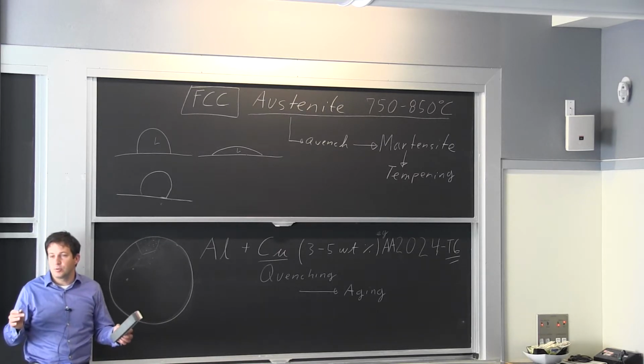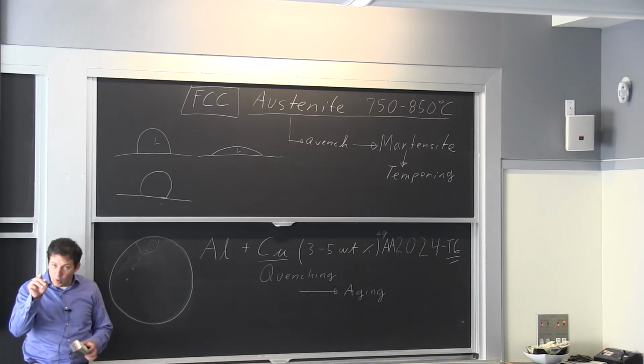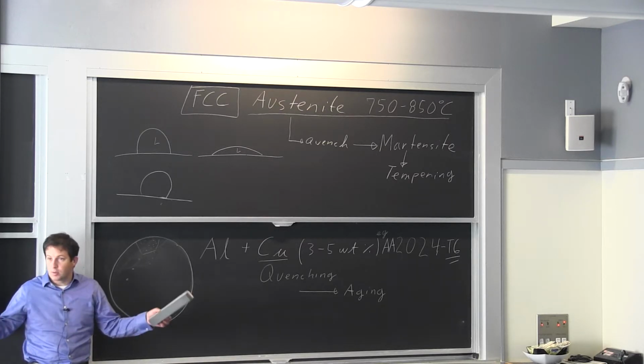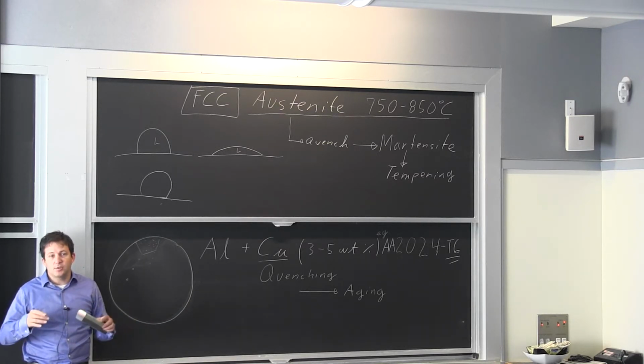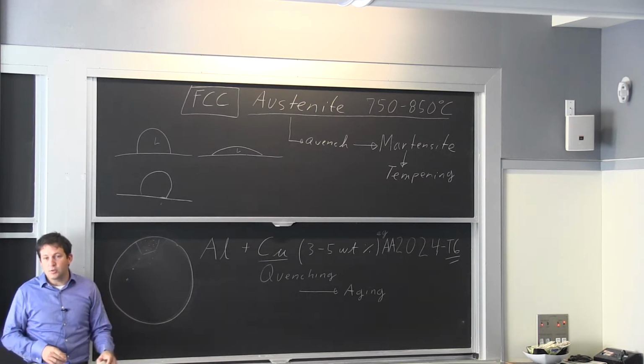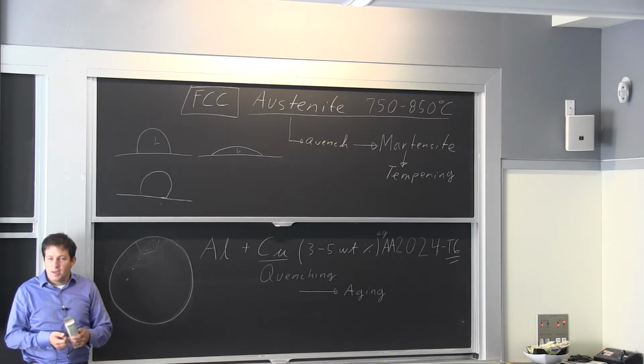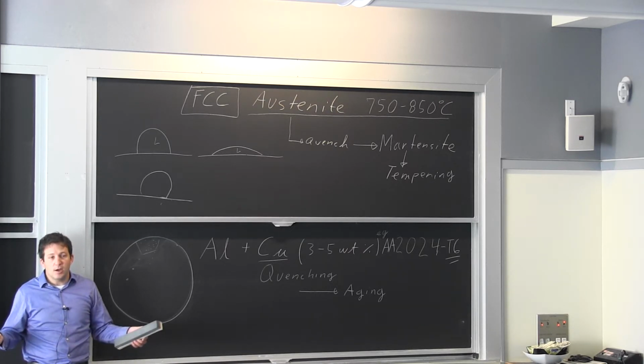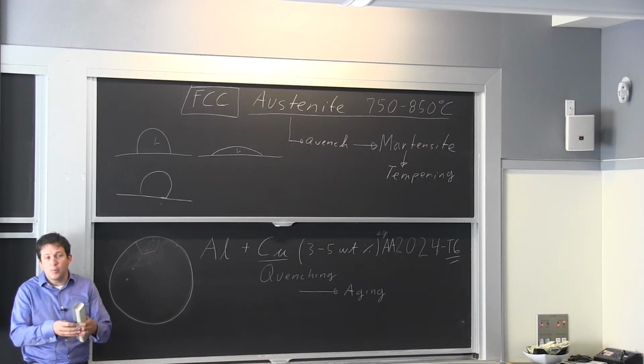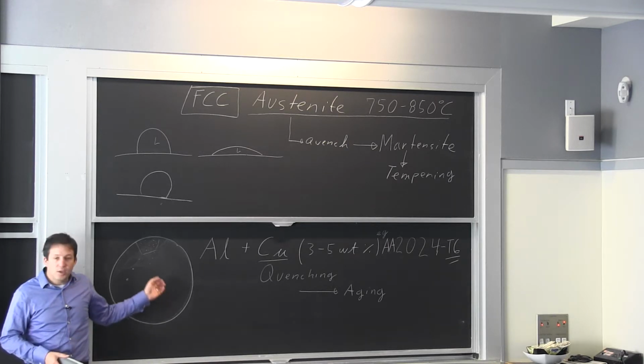If you're at high temperature, you have so much diffusion that if you have one little particle that starts forming, it's going to grow on you. And therefore, we can't just do it by cooling. That's why we quench. And when we heat back up, the condition we have is there's a big driving force. There's a lot of reduction in energy to be gained by combining everything. At the same time, it's a lot harder to get all the atoms to be at the same point at the same time. We don't have as much noise. So when the noise takes place, oh, I'm forming one. But it doesn't really grow very quickly, and that's why you get many.